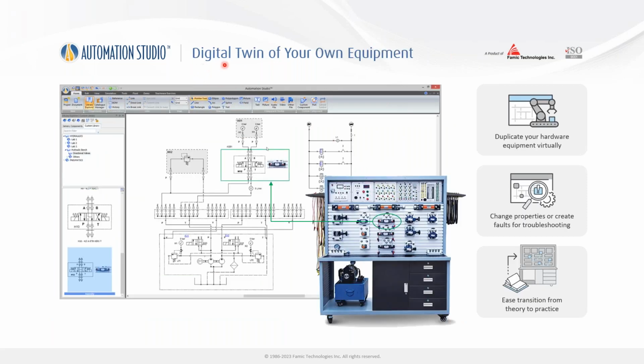You can also create a digital twin of your own equipment. So if you are using any hardware kit like this, you can link this hardware kit with Automation Studio. You can see the circuit which is drawn on the hardware kit, and the similar circuit we have drawn in Automation Studio, and we have linked this circuit in Automation Studio with the hardware kit with the help of OPC server client. So like this you can create the digital twin of your own equipment.